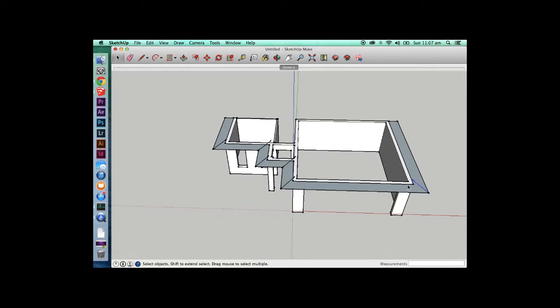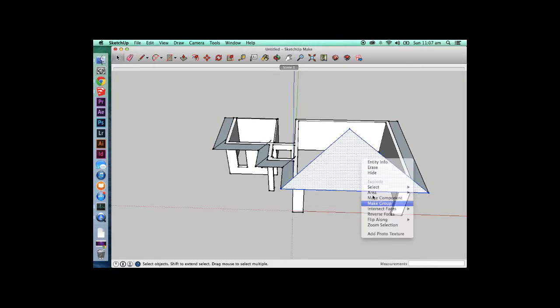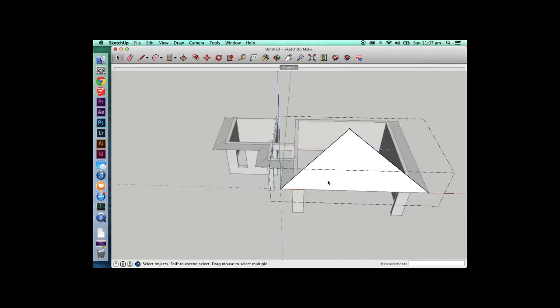Now if we grab this corner, scale it the same way that we were doing before, so it's kind of a proportional scale. Scale it up pretty far. Grab this one, scale it, intersect, and delete these two end bits, and then join them. And that's the first plane for our roof. So group those together. I'm going to open the group and come here.